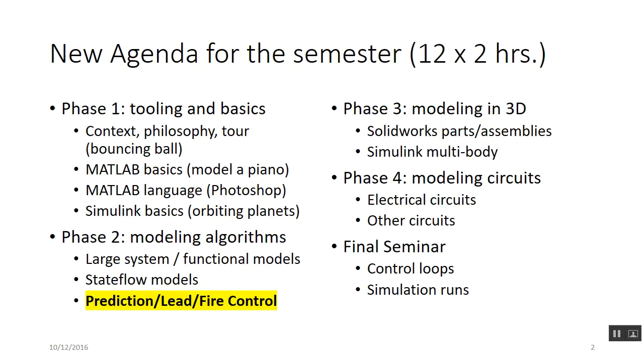Yeah, Ron. So is there a method for connecting to Inventor? Yeah. Simulink Multibody has an import mechanism that can pull in from Inventor and SolidWorks and other places. And in the worst case scenario, you can export from Inventor out to STEP or STL or things like that, and then import. So there's ways around it if I can't find a direct connector.